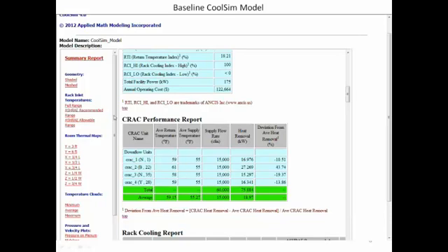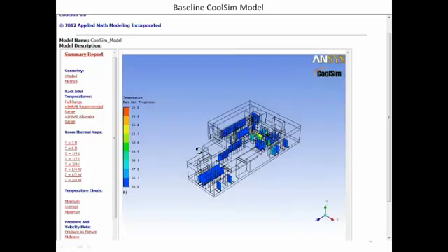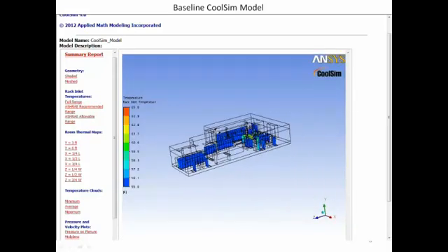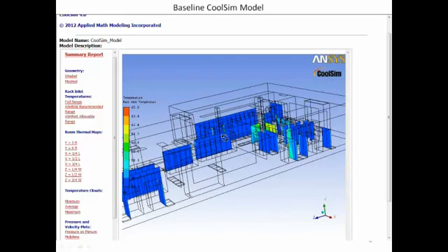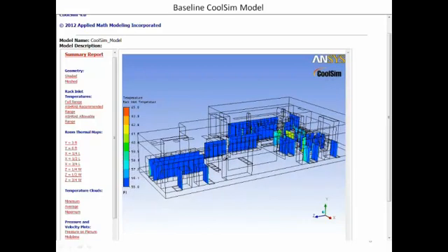So now we've added a couple other things here that might be of interest, and I should just explain. One of them is we've always had the rack inlet temperatures, the rack inlet contours, and these are the temperature profiles of rack inlets. They are color-based profiles or contours, and they're showing you temperature as a function of color. And they take the range of temperature that is measured in the room, the high and the low, and they spread a color spectrum out across it.